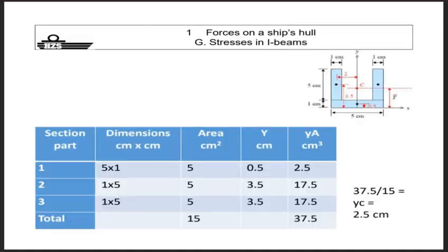Calculating that distance Y, you do by multiplying the areas of the segments by a distance of your choice. I usually take as reference the base of the entire profile.